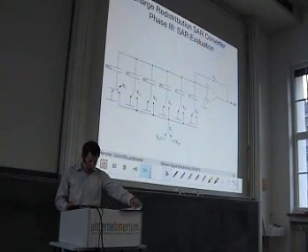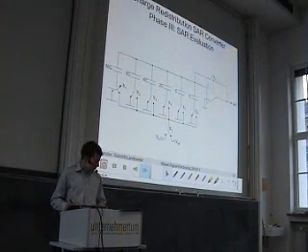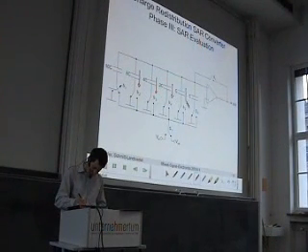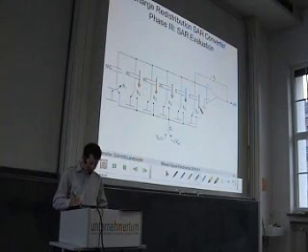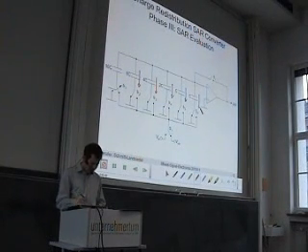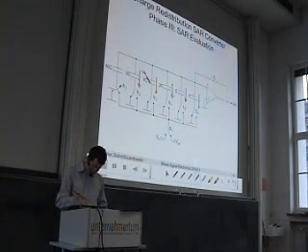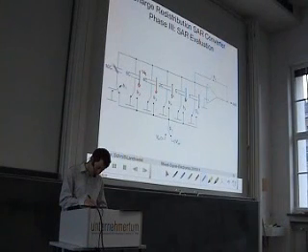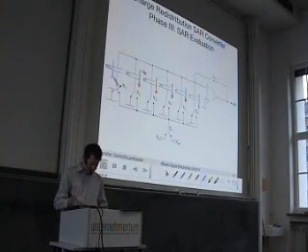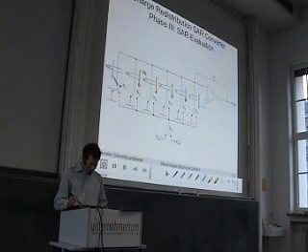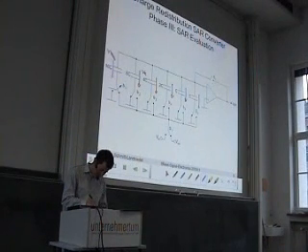Okay. Now, what is the voltage drop across the caps? Still, we have here all caps connected between X and analog ground. So here we have this voltage equal to Vx. However, we have one cap here. This one is connected between the node X and the reference node. So we have here Vx minus Vref.